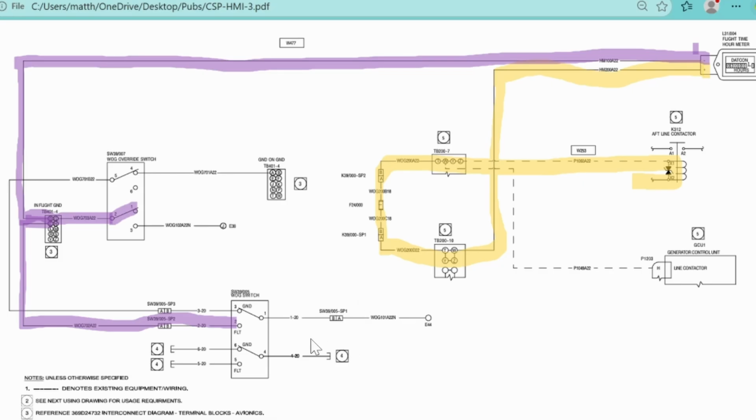So as you can see, the weight on ground switch is open. The electricity can't go anywhere. That's because the helicopter is in a state that it's on the ground right now. So the switch is currently in ground mode. If it were in flight mode, this switch would trigger down. The electricity would travel out to the right and end up at E44.